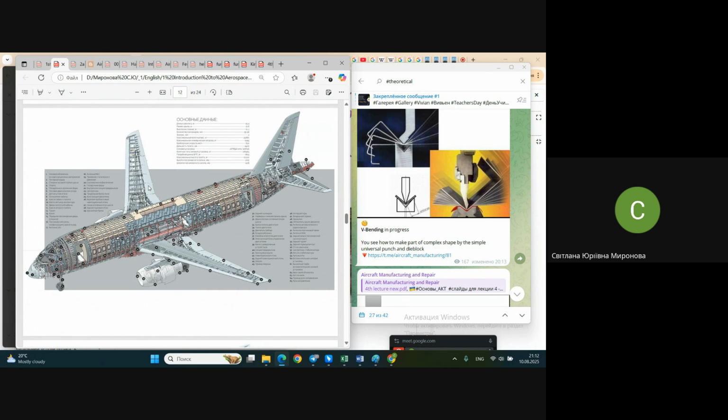The spar goes through and the rib may be divided into 3 portions, into 5 portions, depending on how many spars you have. And in case you have here either a flight control or a high lift device, it will already not be a tail rib, it will be some more little ribs inside of this flight control.